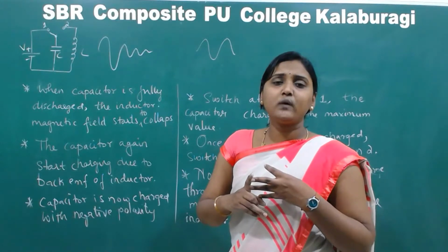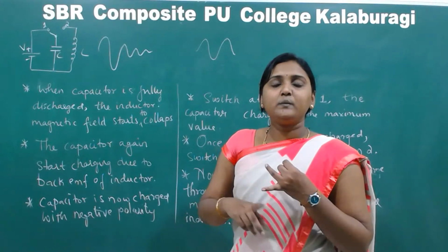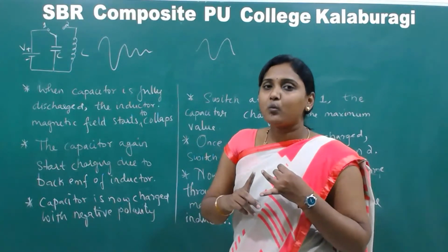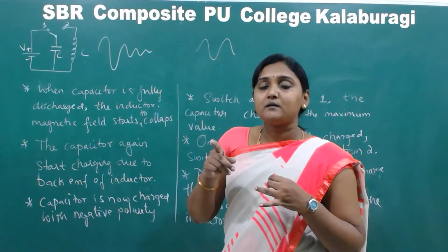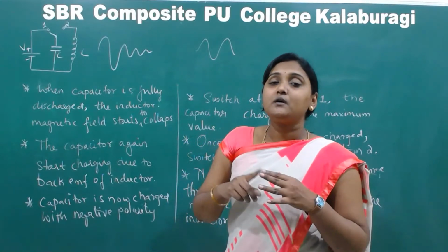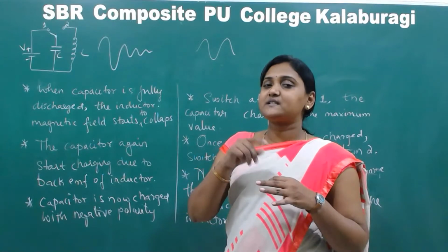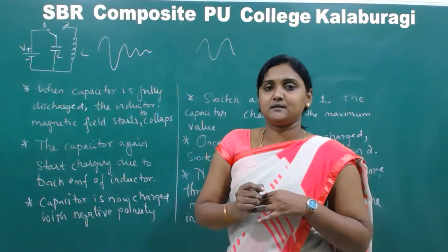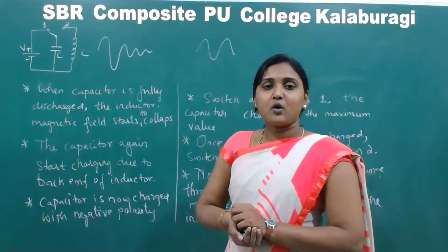A beta is equal to 1, feedback is positive. It has only two conditions. The open loop gain A beta has to be equal to 1, and the feedback connected to the amplifier has to be positive feedback. That means the overall phase difference has to be 0 degree or 360 degree. Right? So this is about the tank circuit and its operation.